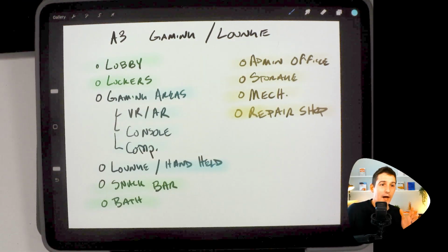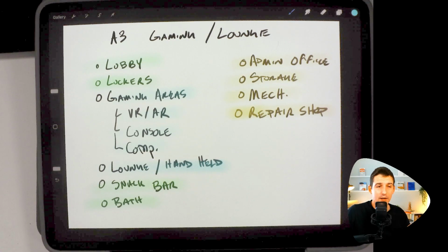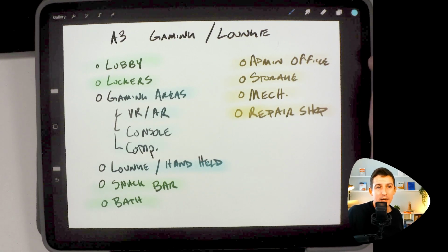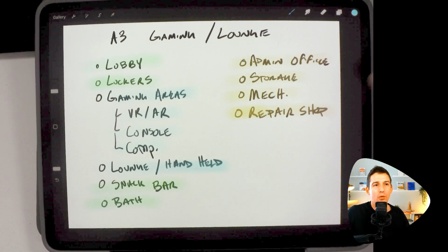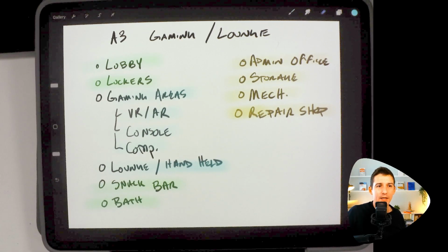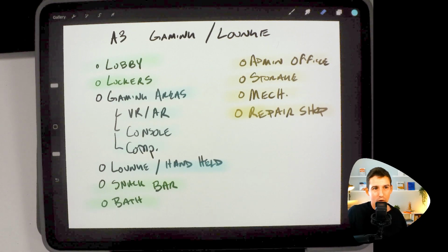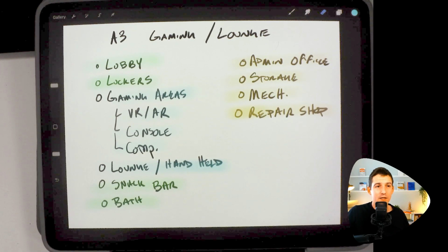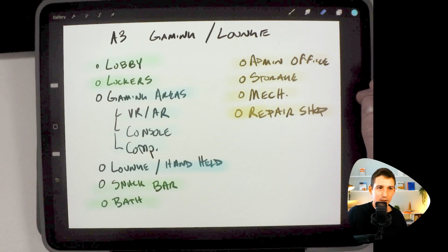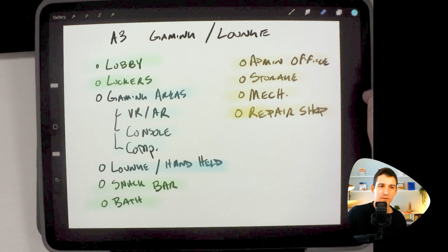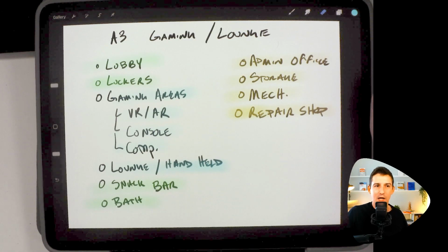This is now how I'm thinking about my bubble diagrams. So in the bubble diagrams, I can go two different routes. I can go by name of room, or I can go by type of room, depending on how I want to organize. In a really large building, with a huge program, I would suggest color coding, and first make your bubbles based on color, and then subdivide those bubbles into the specific program that you were thinking to include. That just makes it graphically a whole lot easier to lay out the adjacencies of spaces and where things need to go.